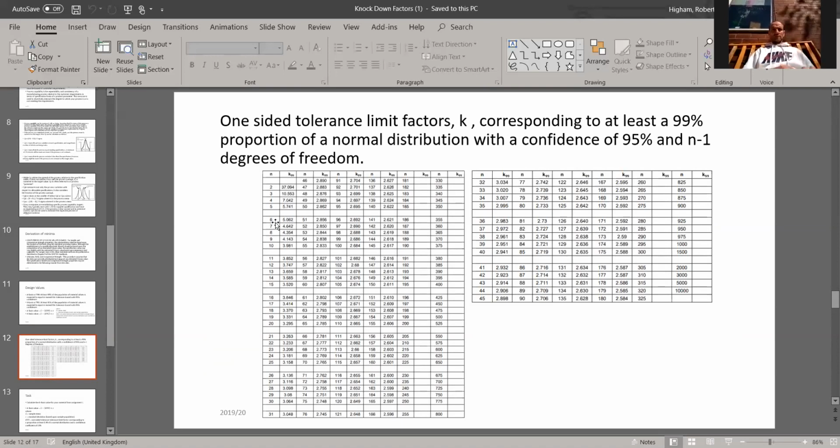So we end up with an A-basis calculation of less than 750 megapascals. If we did exactly the same test, but we did it 100 times, then we dropped to 2 and a bit. So then we can reduce that just because we give ourselves more confidence from more data. You'll see that even for the highest we've got, 180 is 2.5, and then 90, 2.7.